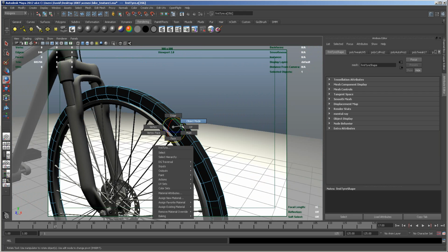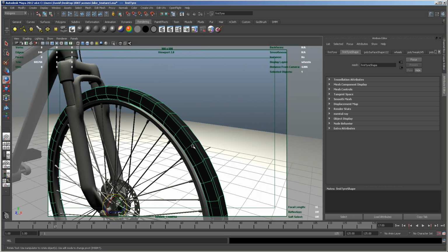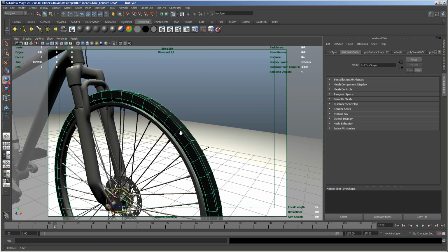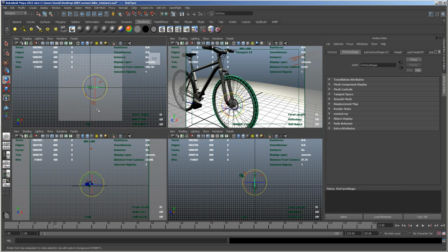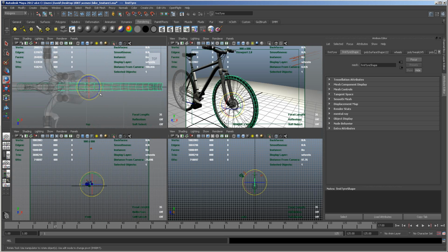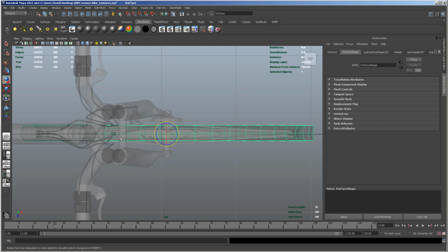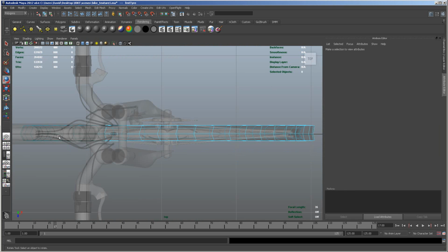Okay, so to be able to do that, first of all, we were in 3 on your keyboard, which softens it. You need to press 1 on your keyboard to come out of that soften mode. And what we're going to try and do is project the sides. So to be able to do that, we need to select the top faces. So I'm going to come into top view, and I'm just going to zoom down to it. Then I'm going to right hand click and choose faces.